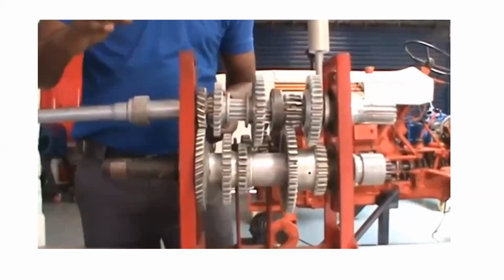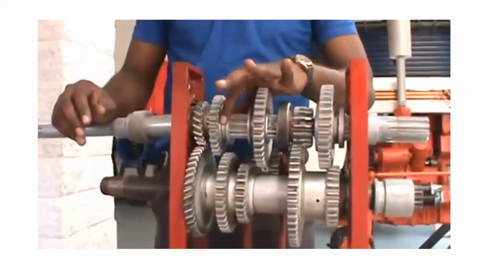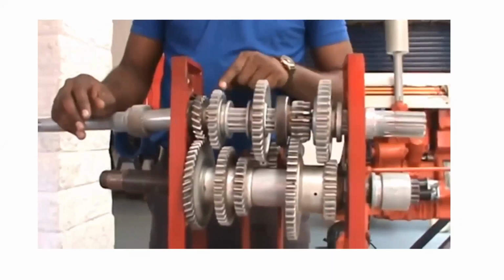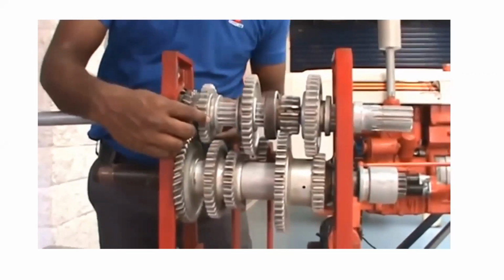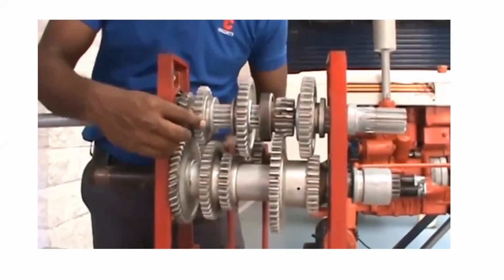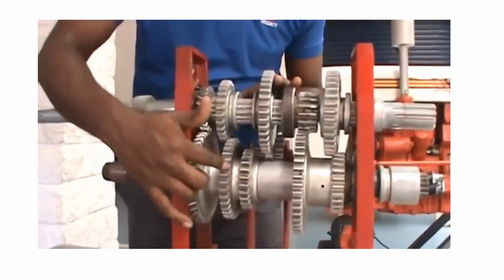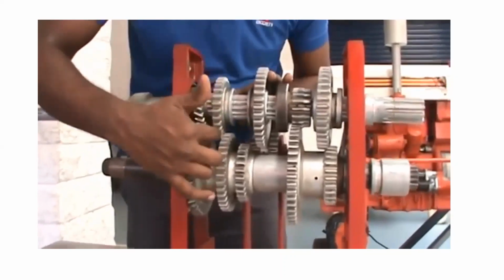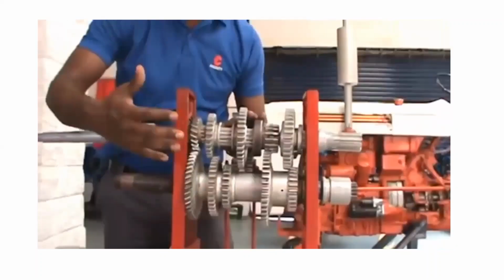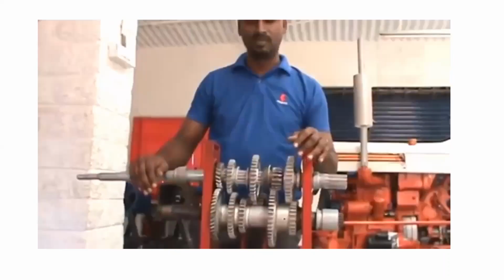So whenever we are shifting the gear, whenever we are moving the shifting lever, the coupler is connected to the gears. So this coupler is connected to this main shaft gear, it's an integral part. So whenever we are shifting the gear, the entire gear will try to come and engage with this counter shaft gear. The RPM of these 2 gears are different, but still we are trying to engage these gears. What will happen? There is a higher possibility of gear to gear clashing. So that will make hard shifting, noisy shifting, and the chance for gear damage is much higher.